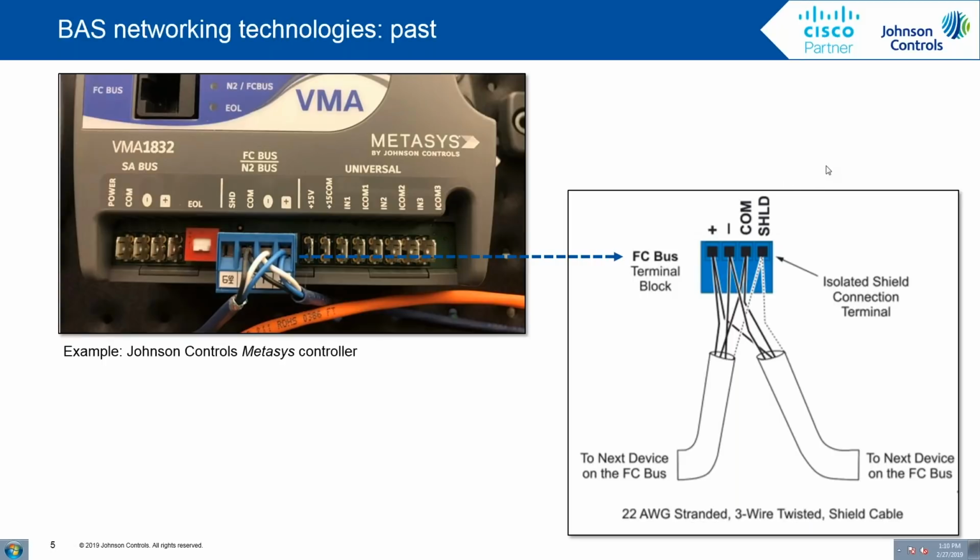Sometimes these field bus networks can develop an open or a short or a ground loop, and then finding those occurrences, finding those opens or shorts, can be kind of difficult, especially given the lack of industry standard tools that are available to troubleshoot those networks.